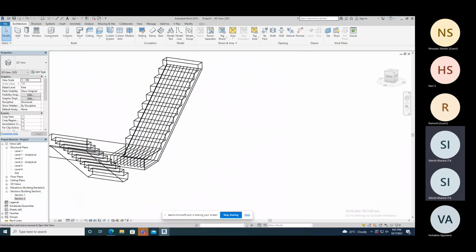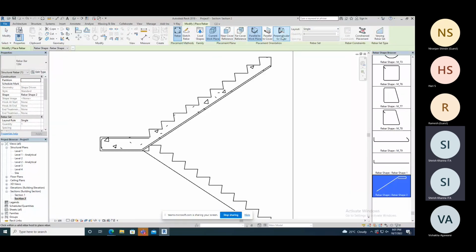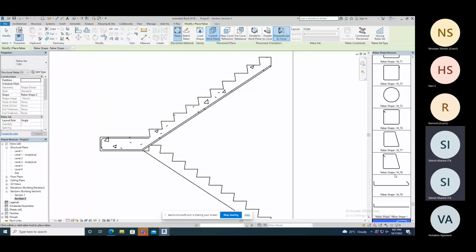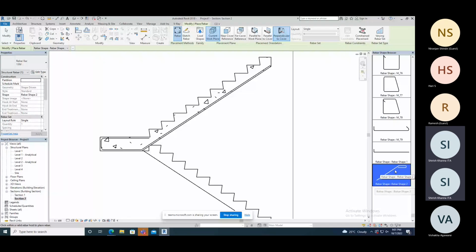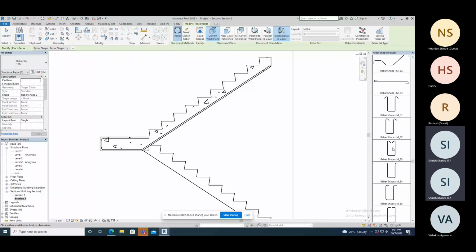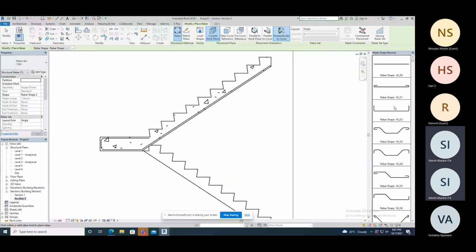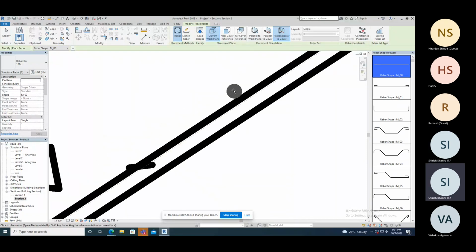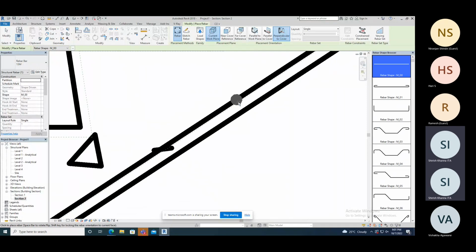You have to create the perpendicular bar. In the same way, select your stair, go to rebar, and now we have to choose perpendicular. See, the rebar shape is visible here also. So the shapes you have created are all placed in your family also. Perpendicular of it we can't use, we have to choose this one. Now we can use perpendicular, so multiples we can create here.